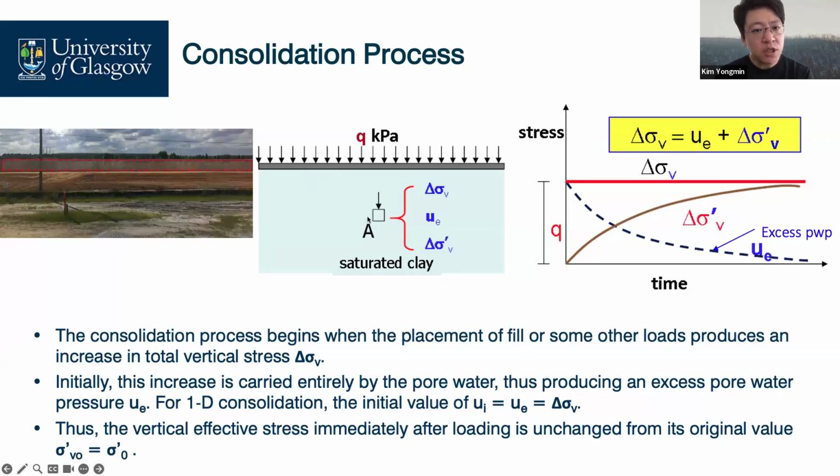Still, hydrostatic pressure exists, and then you apply this Q, so the water has to resist this Q. So your pore pressure increases, which is the excess pore pressure. Then these excess pore pressures gradually dissipate because the water squeezes out here.